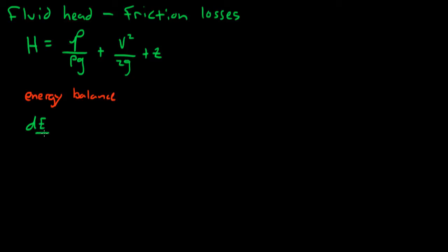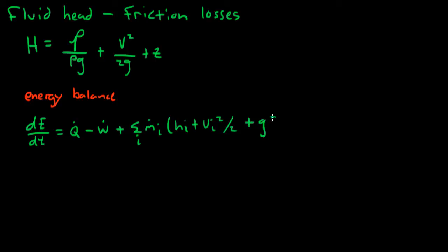Let's start by writing the energy balance for a steady flow in a pipe with friction. We can treat the friction effect as a heat transfer rate rather than work. Intuitively, we can think of this as the effect of rubbing your hands together, or the brakes on a car. The result of the friction force can be treated as a force times a distance, or as a heat transfer. An energy balance would show that they were equal. We'll use a heat transfer model here because it will give us additional insights into the friction effect at the end of the analysis.